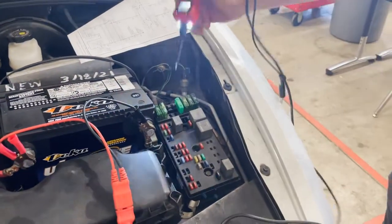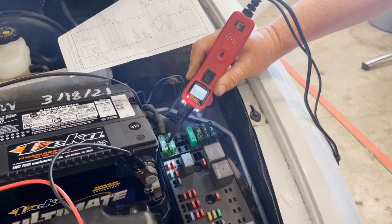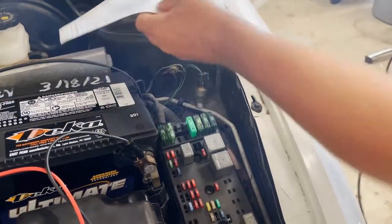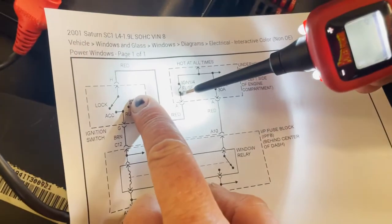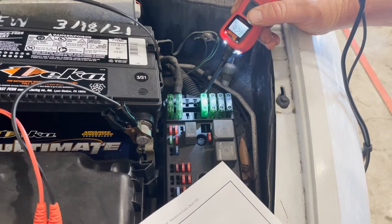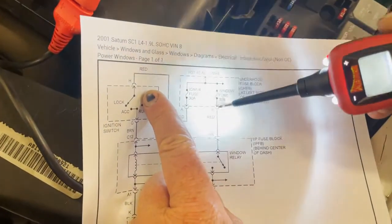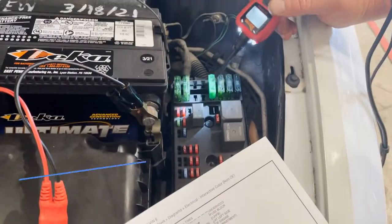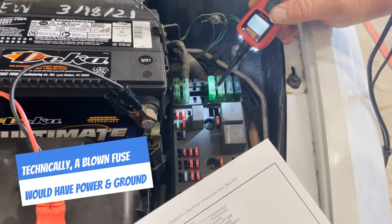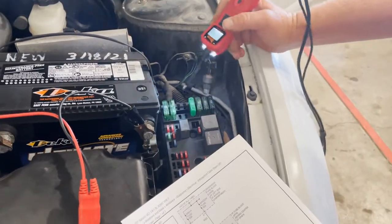Fuses are positive, so I expect to see power on both sides. Power, power. That fuse, the ignition fuse, is good. I have power on both sides. Now let's go to the fuse for the window. Power, power. I had power on both sides of this fuse. If I had power on one side and not on the other, then that would be a blown fuse. But power on power is good, and they're hot all the time.